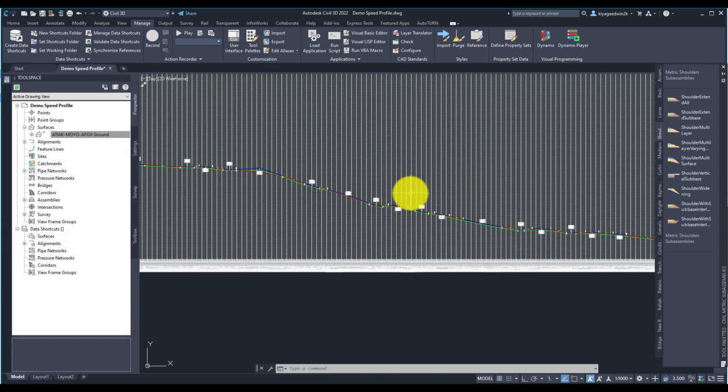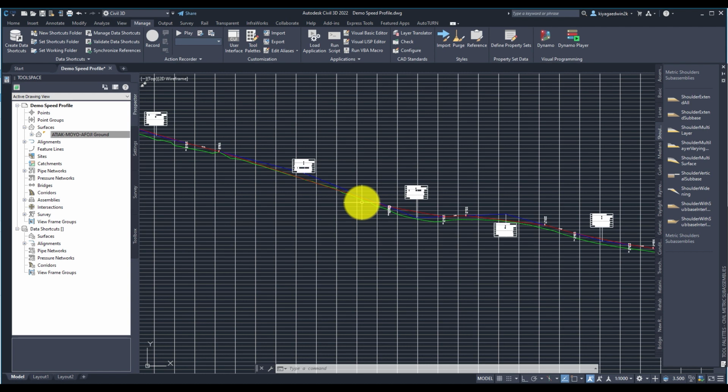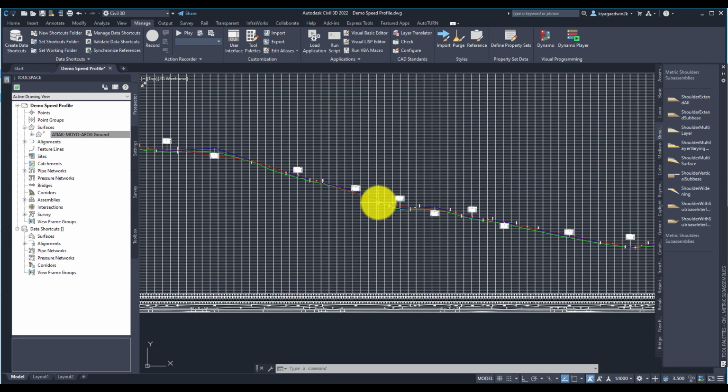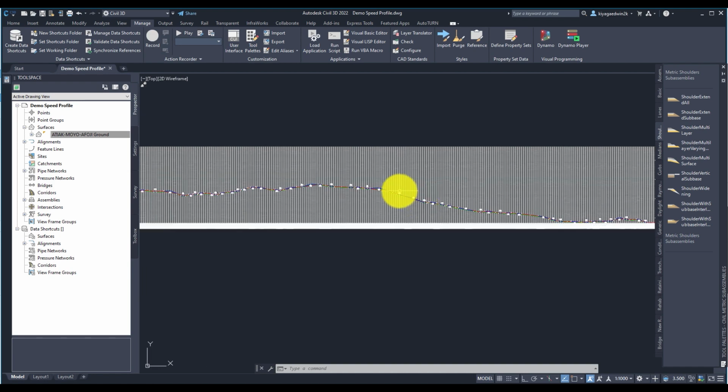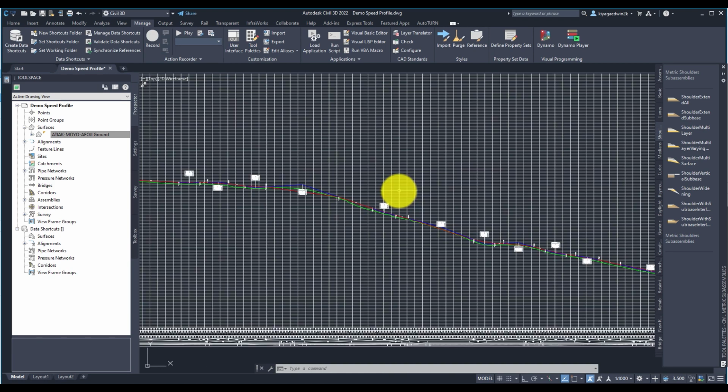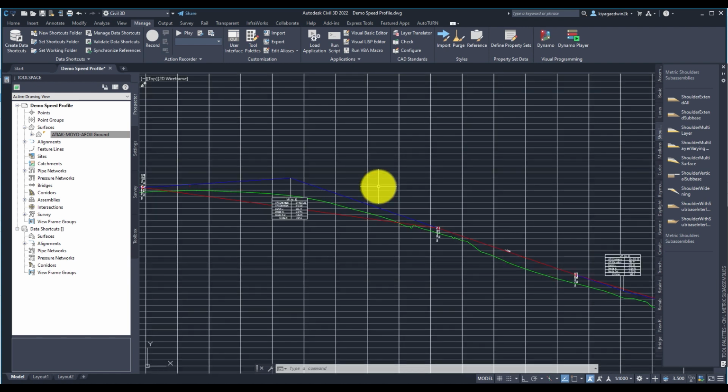Now, of course, if you do a study and you find that maybe the vehicles in this area are powerful, you then have a much shorter climbing lane. And now all you have to do is go into your drawing and draw the climbing lanes. Now, drawing the climbing lanes would maybe be for another lesson. The purpose of this was just to show you how you analyze.